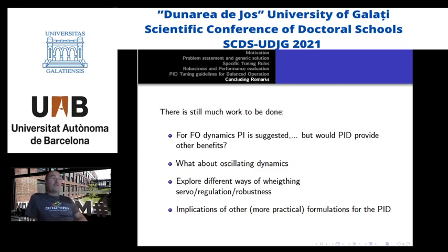And of course, the formulation of the PID, okay? We use the ideal one with filtering in all the computations, to get a little bit more real, but you can use other more practical formulations for the PID, okay? For example, the series one, or the PID with filter, or the double filtering, reference and output filtering for the PID, etc. You get more spaces, more parameters from the PID, okay, but probably you will get more practical information.